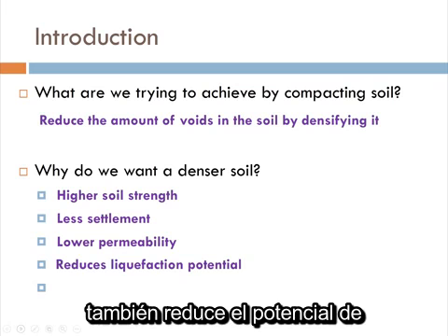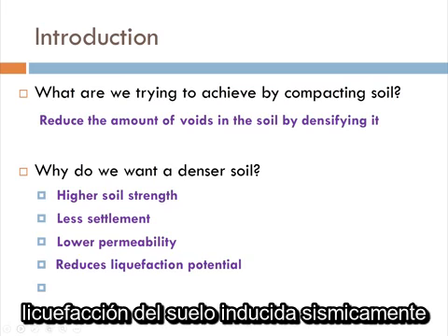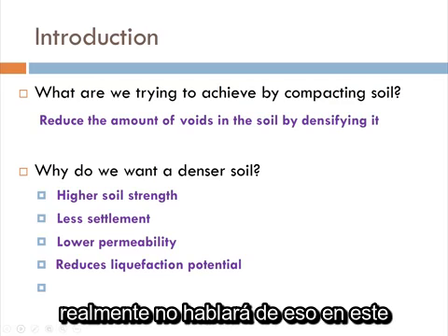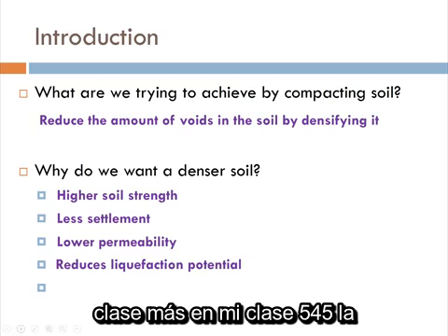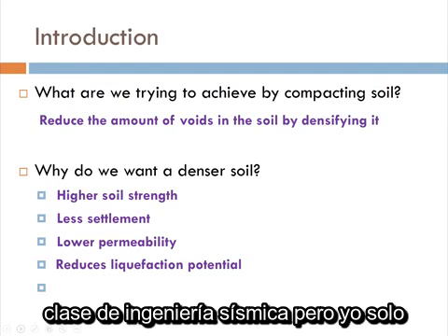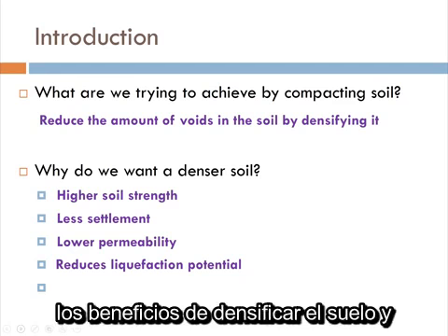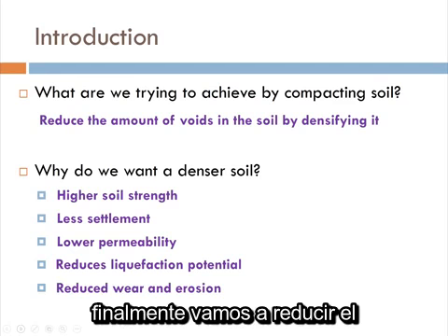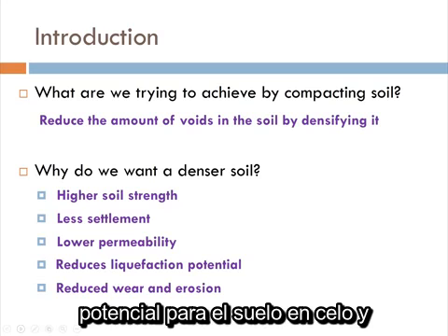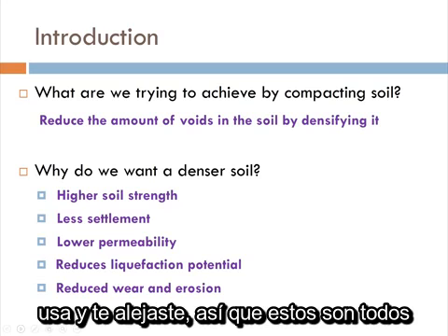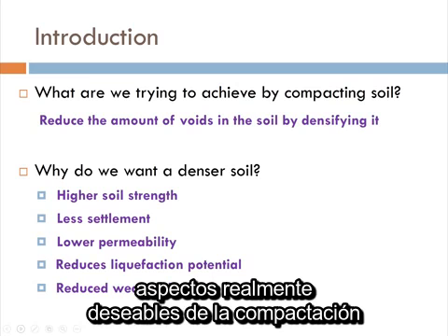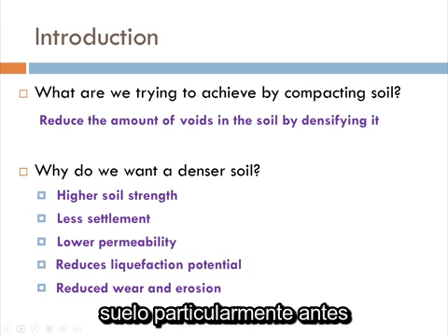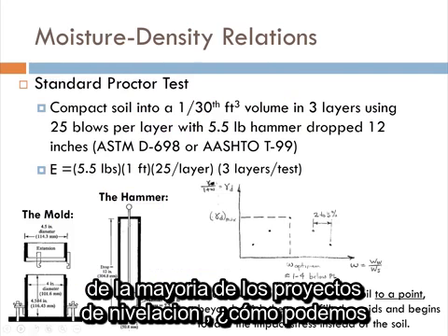It also reduces the potential for seismic-induced soil liquefaction. We won't really talk about that in this class, more in my 545 class, the earthquake engineering class. But I just want you to be aware that that's one of the benefits of densifying soil. And finally, we're going to reduce the potential for the soil to rut and to wear and erode away. So these are all really desirable aspects of compacting soil, particularly prior to any mass grading project.